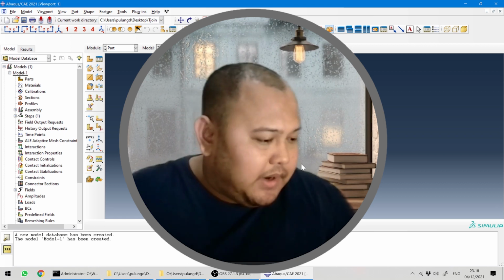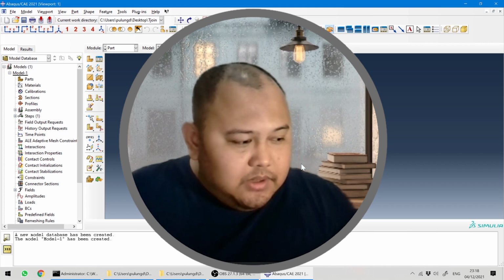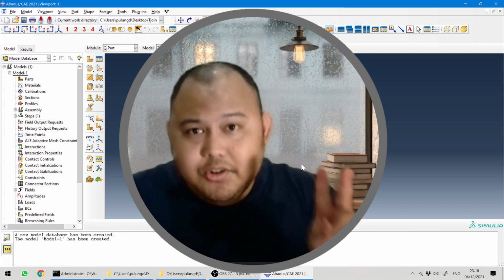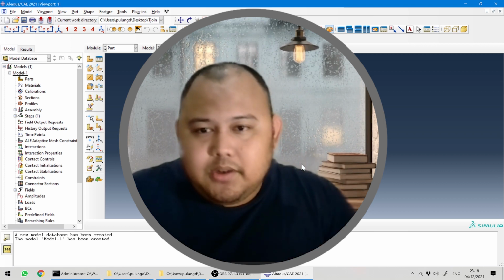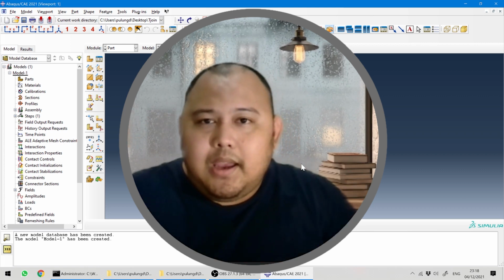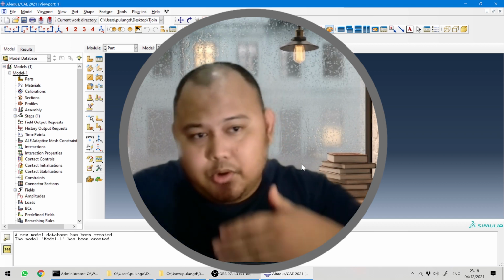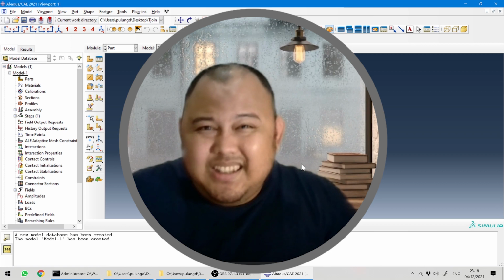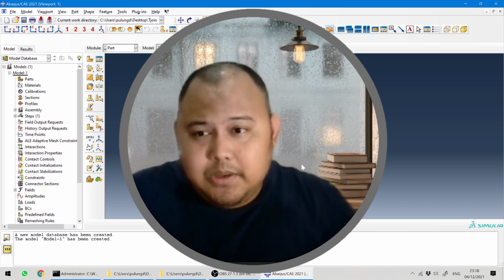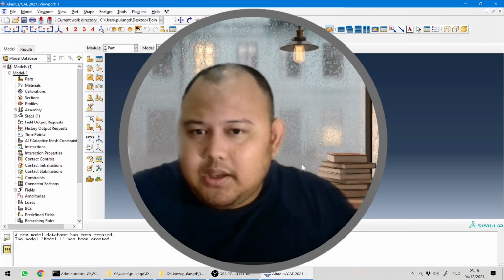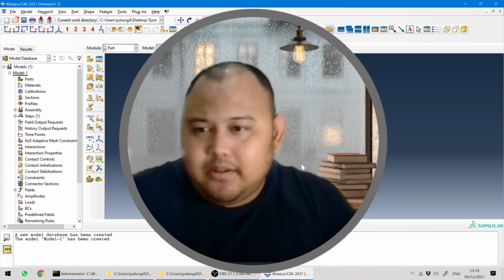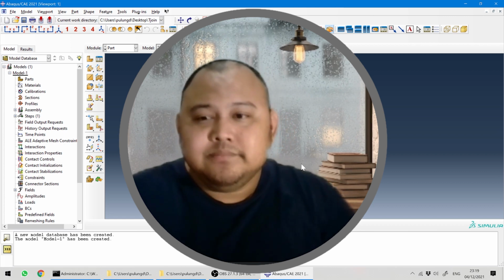So, all right, without further ado, let's continue with the video. I'm going to simulate a T-joint. This series is going to be two parts. In the first part, we're going to model the T-joint, so there will be a composite beam with another composite beam, and then we are going to connect them with adhesive, especially in Abaqus. We are going to use a cohesive surface-to-surface behavior this time. Hopefully this will be helpful for you, especially for those of you who want to simulate adhesive debonding, for example delamination in composite.